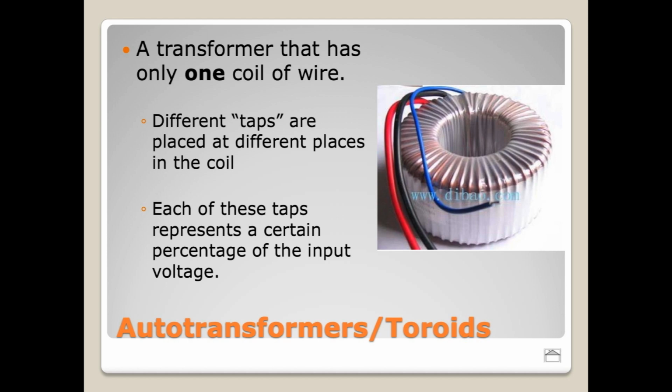They also tend to take up a little bit less space, and they also tend to throw off less electromagnetic radiation, right? They tend to concentrate it a little bit more. This can be a really big advantage for us because if we have this in the power supply of a piece of audio equipment and we have audio wiring running through or next to the magnetic field here, that wire, if it's within the magnetic field, is going to pick up that electromagnetic signal, right?